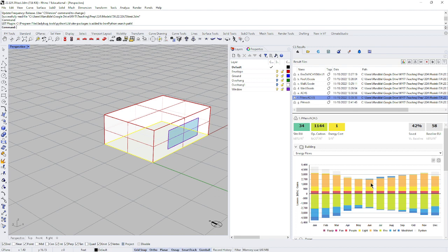So we may be able to fix this. This may not be solar heat gain. It may be lost through the interior. We're at 68 degrees inside, and it's 90 degrees outside, so that'd be a loss. But that's an area we might be able to tweak and try to do some overhangs or mess with the glass.